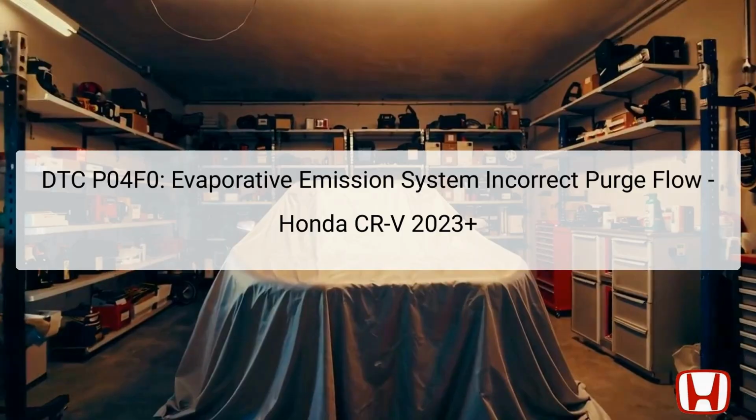DTC P04F0 indicates an issue in the Evaporative Emission Control (EVAP) system related to incorrect purge flow. The EVAP system is designed to capture fuel vapors from the fuel tank and prevent them from escaping into the atmosphere, playing a crucial role in reducing emissions.